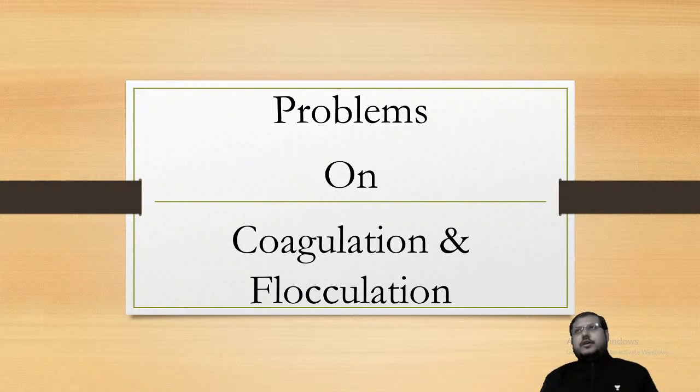All those small flocks will attach with each other and they form bigger size flock. That is called as flocculation. And when they attain enough size and mass, they will get settled down. It will be called as the settlement or sedimentation. And type 2 settling process or flocculant settling will be observed.